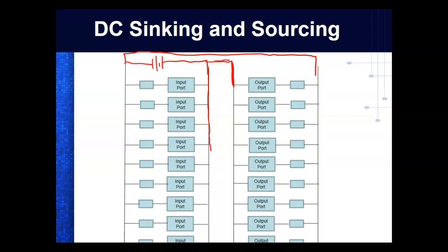It can run some inputs and some solid state sensors, but it can't run more than that. So normally what you'll find is the PLC will have an external power supply. In fact, both the lines we looked at the other day have an external power supply. That way you specify what power supply you need, as long as you don't exceed the rating of these guys right here. These are going to be rated to provide a certain amount of current.